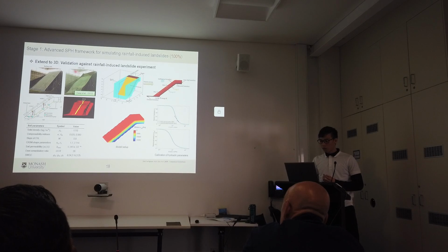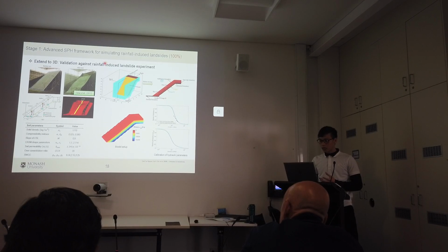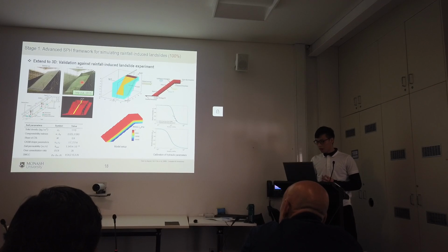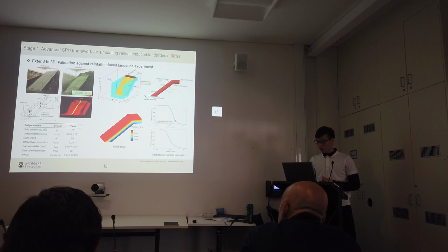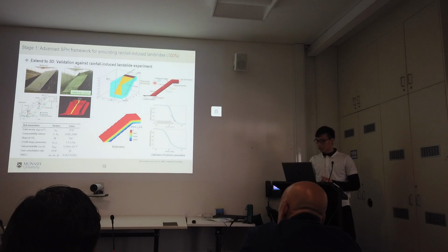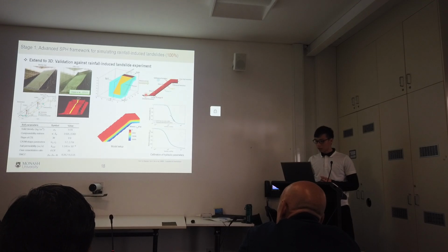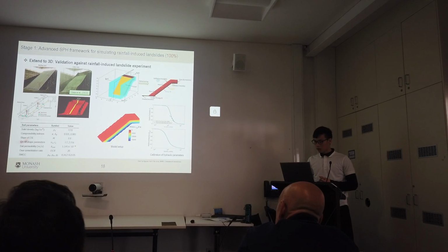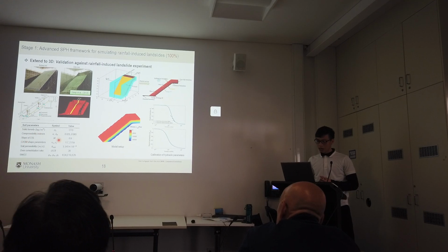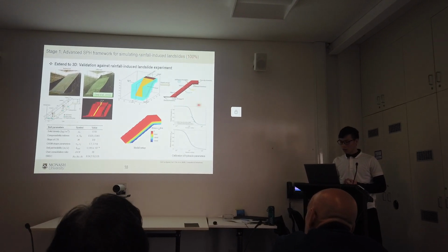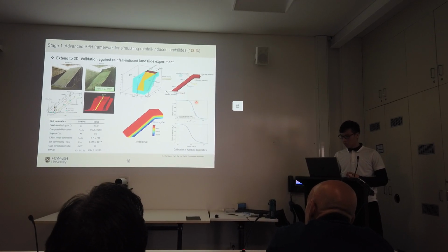We have also successfully extended our model to 3D simulation. Here we verify again the Damiano et al. 2012 experiment. On the top right is the model setup where rainfall is applied on surface particles. On the bottom left is the table showing information that enables us to calibrate the constitutive model and the calibrated curve that you can see here.